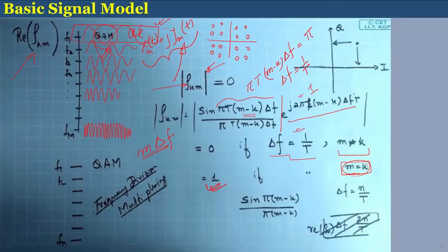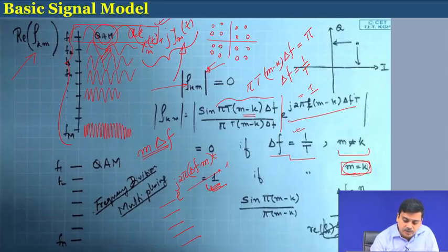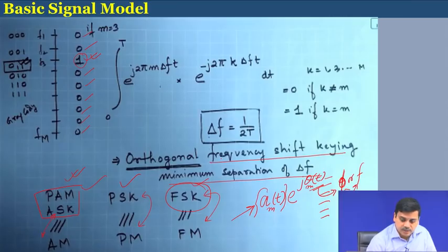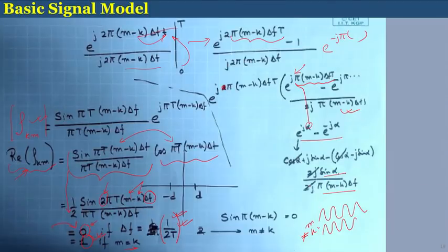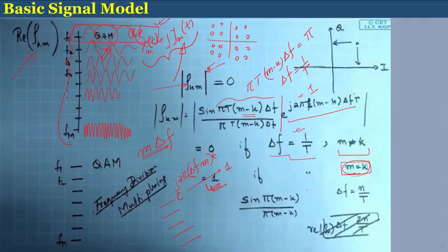So, in other words, the receiver, even though it gets all the signals, in this case we have to have m number of correlators. Each correlator will be correlating with e to the power of j 2 pi delta f times m times t, okay. And hence, each of them is going to produce a magnitude of 1, because our correlation expression we have taken as S_l_m(t), S_l_k(t), but now we would also have this additional x_m plus j y_m term along with that.